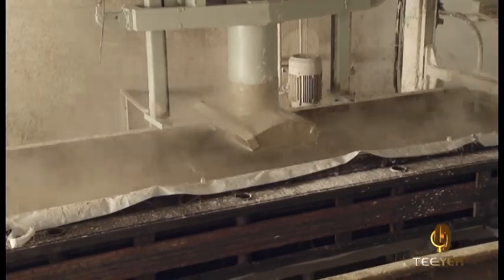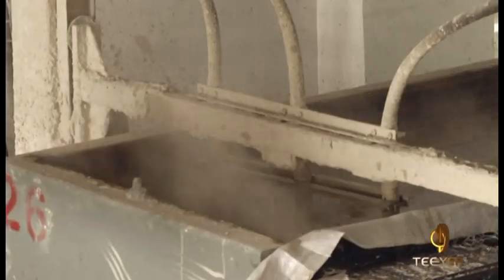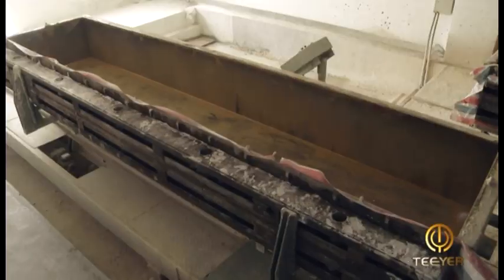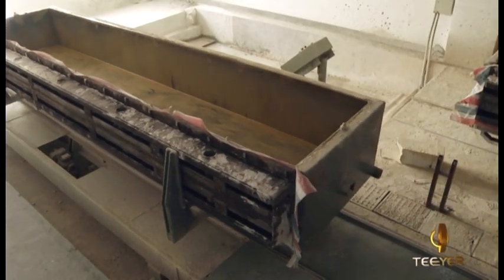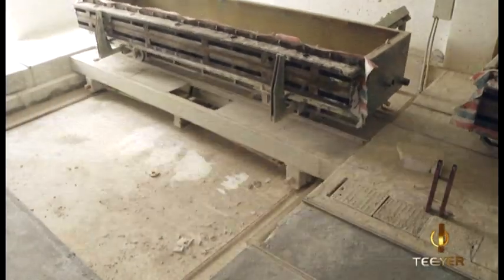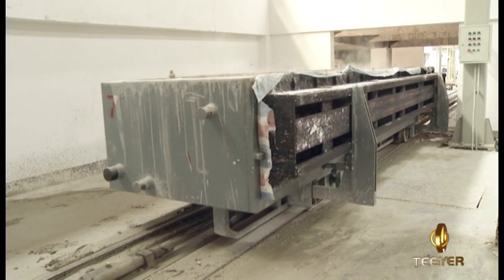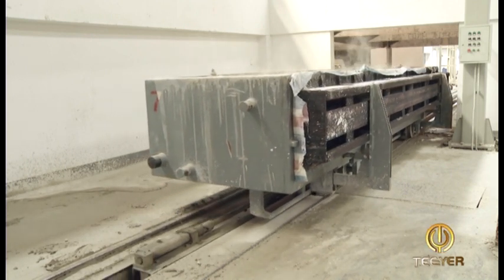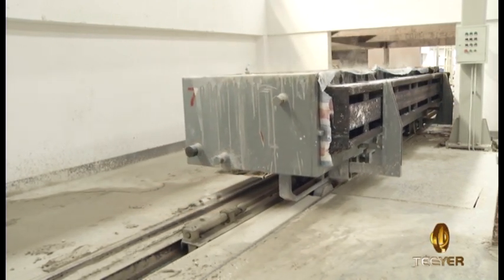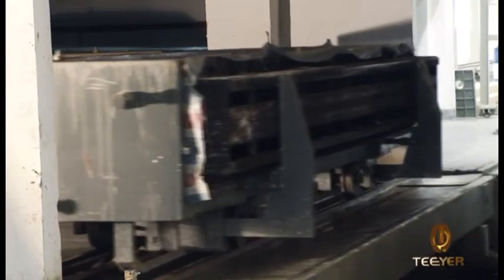Bubble process machine vibrates with slurry in the poured mold to remove big bubbles. Meanwhile, another oiled empty mold is transported by ferry cart to the position under the pouring mixer for the next pouring. The mold in which the air bubbles have been removed is conveyed on the ferry cart through the friction wheels and transported to the rail for pre-curing.